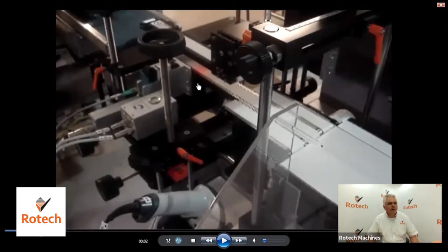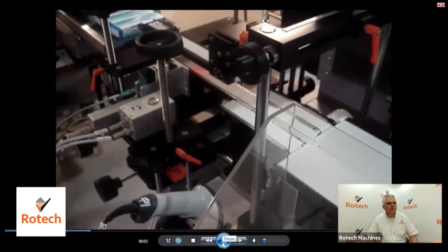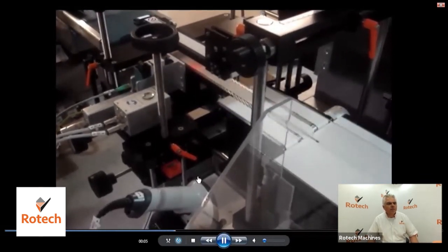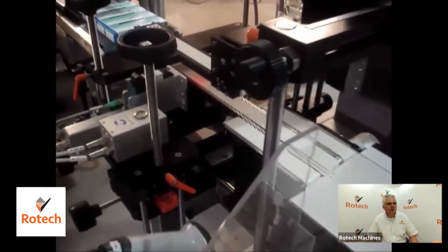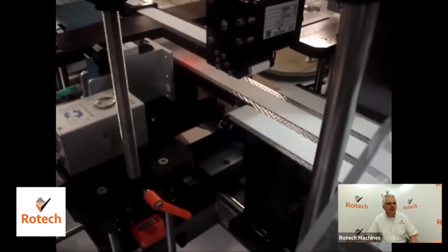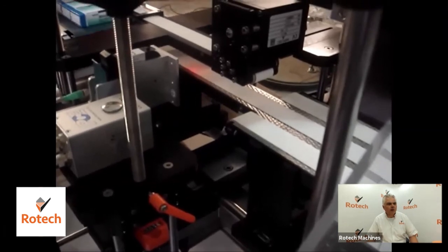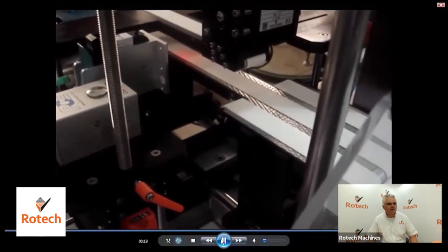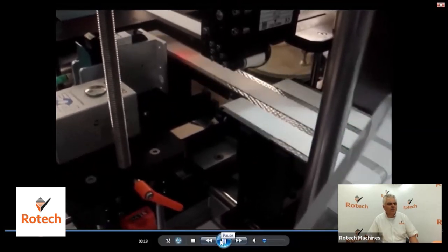And then talking again about carton presentation, this is doing everything it can to keep the carton nicely presented as it goes past the printer. So let's put some through. So there's a top belt which keeps the carton nicely secured and driving past the printer. One of the challenges is to make sure that the carton doesn't bow. You want the surface that's being printed on to be absolutely flat as it's going past the printer.